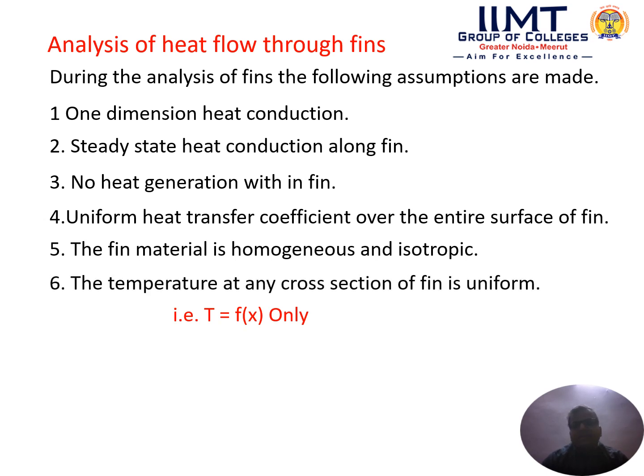The temperature at any cross section of a fin is uniform. That means at any value of x, the temperature of that section will be uniform. That means the temperature is only a function of x. It is not a function of time. Let us suppose this will be the fin, and this is the x.